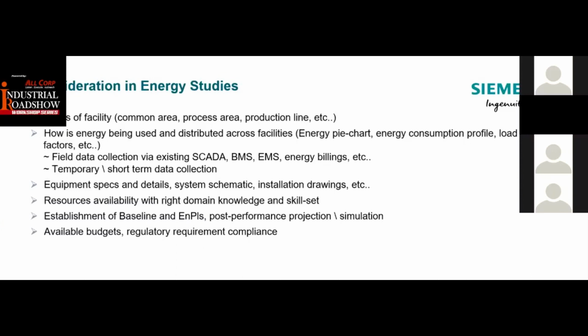And that boils down a lot to how much budget is actually available. To conduct a full detailed audit itself is not cheap, the reason being the deployment of instrumentation from the service provider and the amount of effort required, not just to purely get a temperature of the space. At times, we may even be required to shut down a system to install a power meter, for example, or we need to open up your installation either on a hot water system or on a chilled water system to actually install the instruments. So all this requires cost, and that's actually why it will not be a free service.